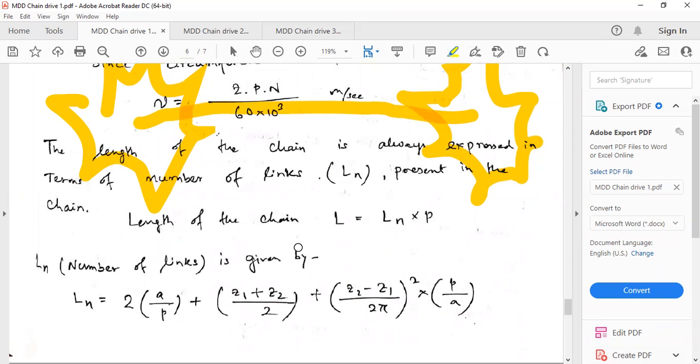Okay, your center distance, you just decide. As a designer, you are designing at the beginning, so you have to make decisions like what should be the gap between the sprockets. You decide the gap first, the center distance, and based on that you calculate. If you see this is not sufficient, that it doesn't fit there, then you have to modify. So that is what we do every time.